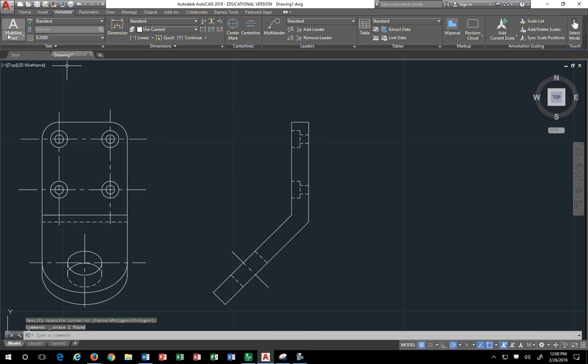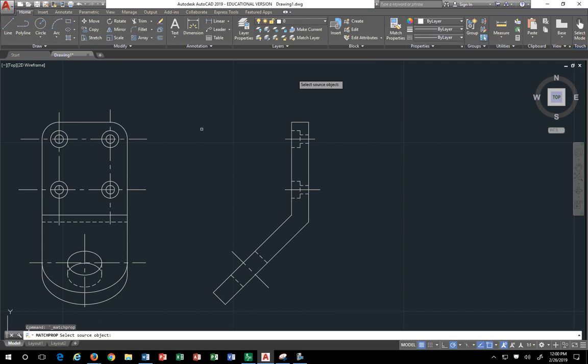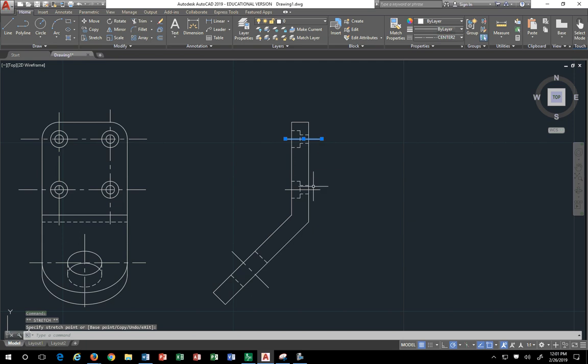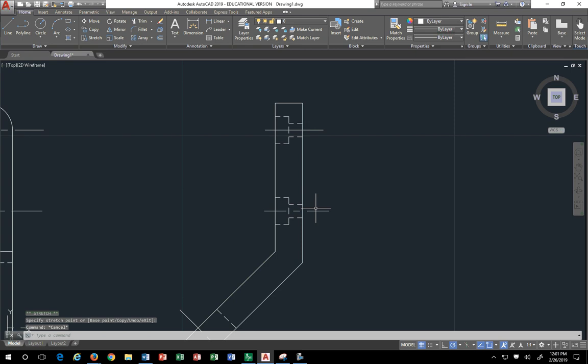So what should I do instead? What I've already done, I'm going to draw the line, drag across. See that? I'm going to draw those instead. And then do a match properties of this center line to this guy. Now these don't change because the lines are really short. Got to extend them a little bit. Question is how far before they become visible center lines. So this one's tough. Those center lines don't want to really look like center lines right away. So what could you do?